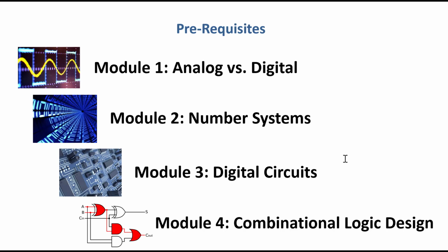This is where we looked at the basic logic operations, things like ANDs and ORs and NANDs and NORs and inverts, and we looked at their truth tables and how they produced an output based upon inputs, but it was all a logic value. And what we mean by logic value is that the inputs to a digital circuit are going to be either a 0 or a 1, and then the circuit is going to compute the output, which will also be a 0 or 1. So when we think about a logic gate, that's the basic operations that can take place on ones and zeros and produce an output. But we wanted to actually build hardware.